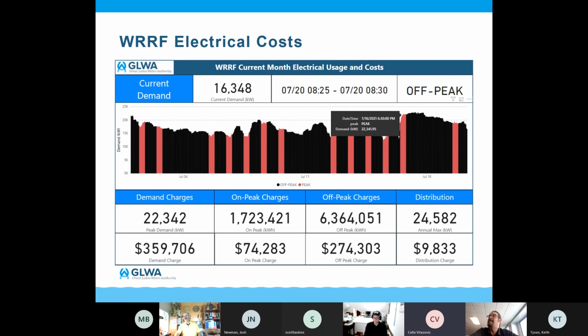Hard to say. I think maybe those are the bottom of our process. So now those troughs could be lowered with some energy efficiency effort. Like one of the things the DTE energy managers brought up is the air system. So here the air system uses almost a megawatt, and those are notoriously inefficient. So like the treasure hunt here, could we look at the air system, walk the air system, look for leaks, and any of those types? Those are overarching efficiency things. But I think this is probably as low as we're going to go without doing energy efficiency measures.